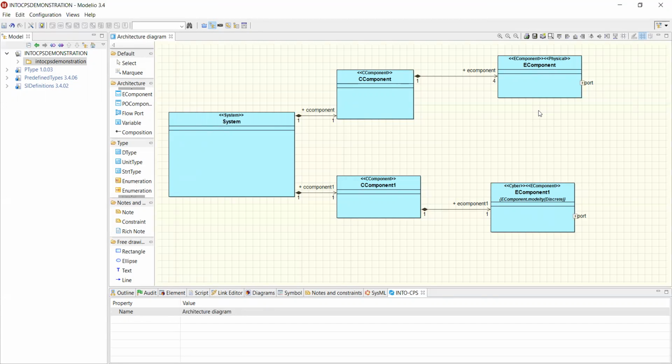But you have to be careful that all instances of this E component will be related to one unique FMU, which means that all 4 instances here will have the same behavior, represented by one file, one C code, in fact, one DLL. So you cannot distinguish any of them. All 4 of them will have the same behavior.